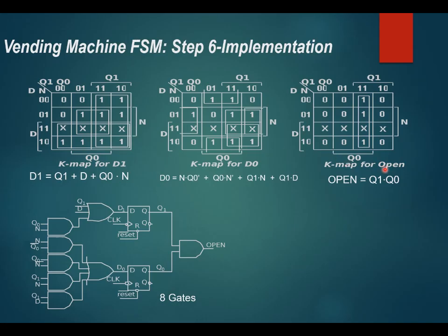The same way, you fill out all the Karnaugh maps, then you solve them using the method you have learned in digital electronics, which is circling for the SOP solution. You circle the largest group of ones, including manipulating the don't cares. Since a don't care can be 0 or 1, you decide it as 0 or 1 to make the groupings of ones as large as possible.